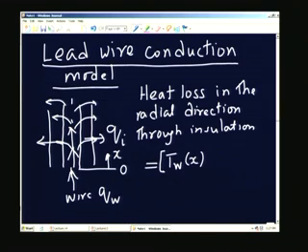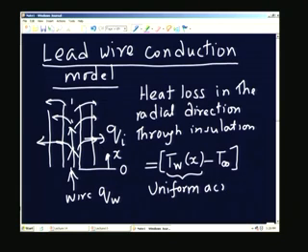the heat transfer is Tw at x minus the ambient temperature, which I will write as T infinity, that is Tw, which is the value at any particular value of x along the wire. In fact, I will treat this as uniform across the wire. That means that the temperature, any cross section of the wire, if you take, the temperature is uniform across that cross section given by Tw, which of course is a function of x.